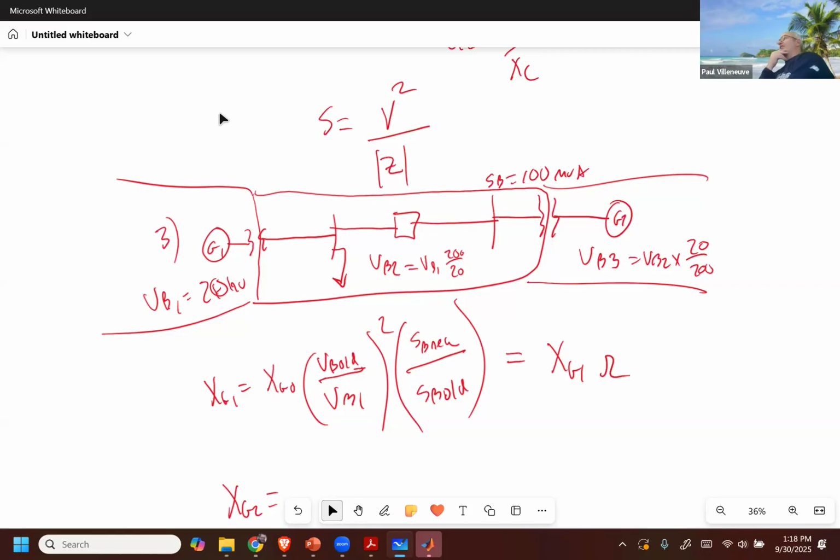All your calculations on the power system are done in per unit because it's too much work to transfer stuff over our transformers. Voltage, current, impedance, and power, all those are done in per unit. If you were to look at a per unit diagram under the hood of a power systems analysis program, they're all without units.